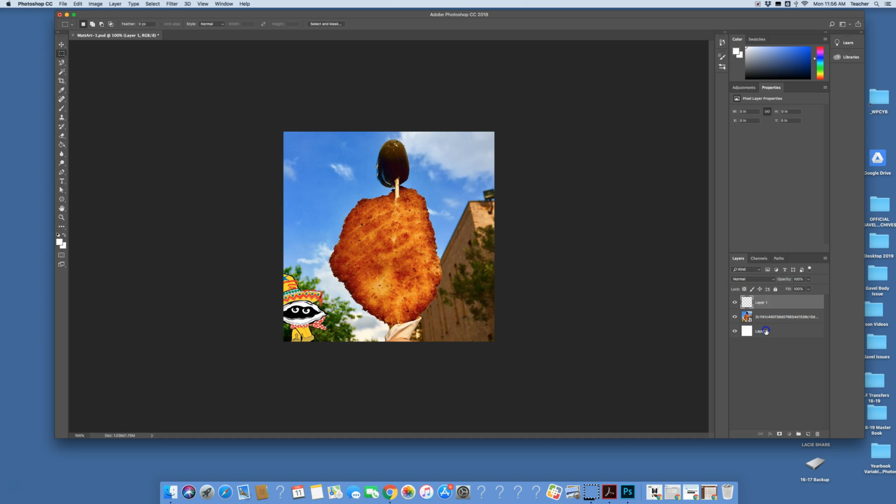You can go ahead and take layer 0 and drag it to this little trash can here, so we should just have 2 layers. Once you have that, click on the layer with the image on it, go to opacity, and bring down the opacity a little bit. I'm doing about 90%. That way when we start drawing our lines, we can see what we're doing.